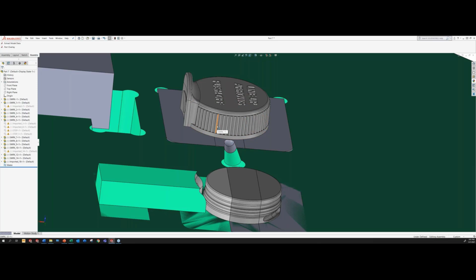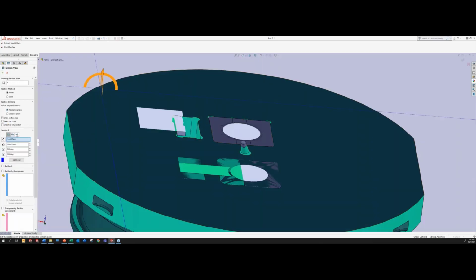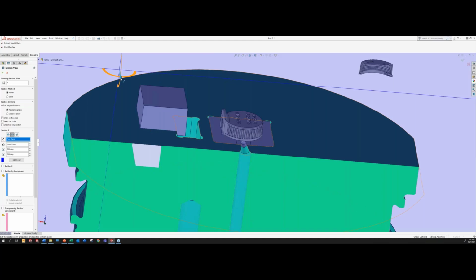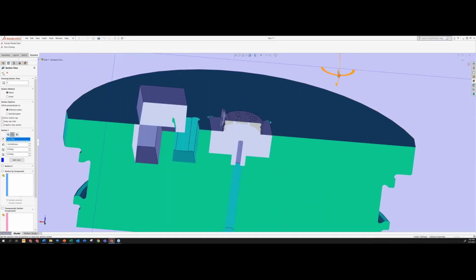If you're looking at the cross section of those three pieces, instead of straight walls, there'd be angles on there, so the center one could pull free while the other two pulled in as lifters and release those undercuts. So it'd just be a slightly different approach, but it is doable.